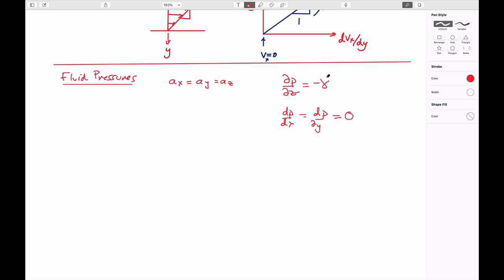We can use this expression either for a compressible fluid, which would be a gas, in which case the density is equal to pressure divided by the gas constant for that gas and the temperature. These have to be absolute temperatures and pressures. And for a liquid, density is constant. It doesn't change as a function of pressure, or changes only marginally. And this defines how we deal with the magnitudes of pressure change with elevation.